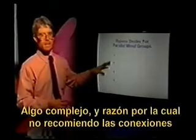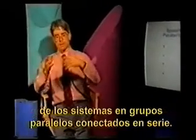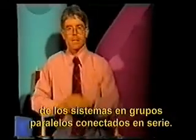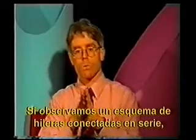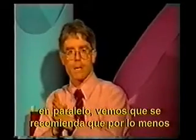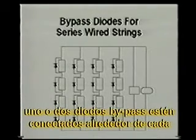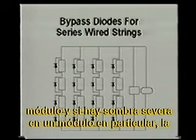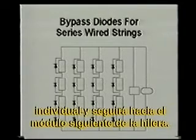A bit about complexity, and another reason why I don't really recommend wiring systems in parallel groups that are connected in series. If we take a look at a schematic of series wired strings wired in parallel, we can see that what's recommended is that at least one, if not two, bypass diodes are wired around every single module, and if there is any severe shading in one particular module, the current through that string will go through that individual bypass diode and on to the next module in the string.